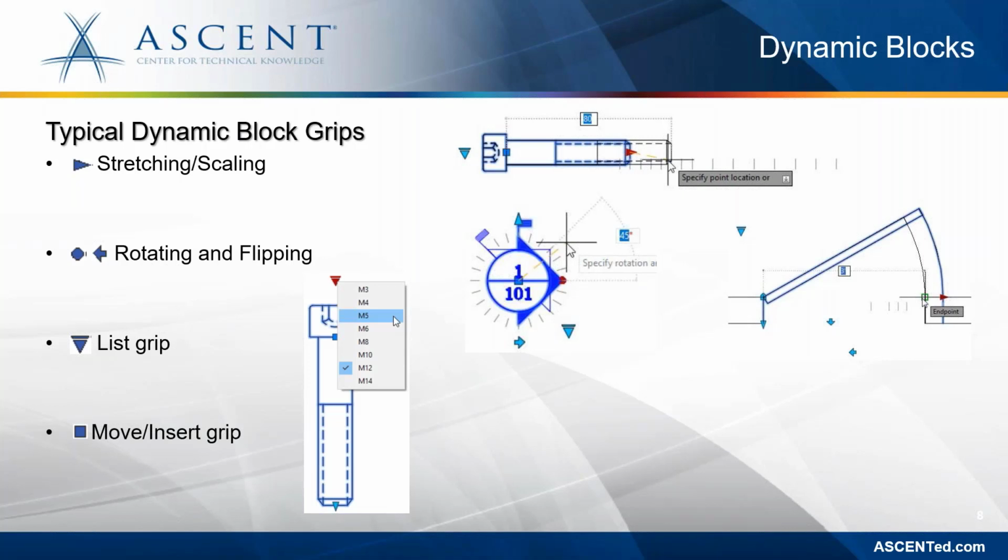Then you can have the circular grip, which is the rotation grip, and obviously it rotates the block object. Flip action flips a block and is represented by a full arrow grip. They're quite important for doors and windows to flip their swing side and the hinge side. So here you can see on the screen, you can flip them so that the swing is on the other side rather than being on the right side.